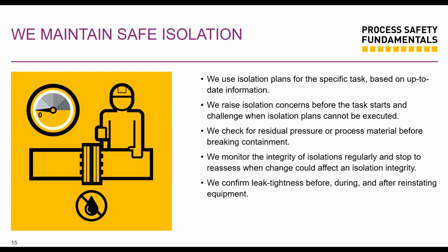So we want to make sure we maintain safe isolation. And what are a couple of examples? So we're working on a steam line, and you want to cut open a steam line. Before starting that operation, verify that the line is fully depressurized, because steam expands very, very aggressively. You want to make sure that that line is fully depressurized. There's no steam in it.